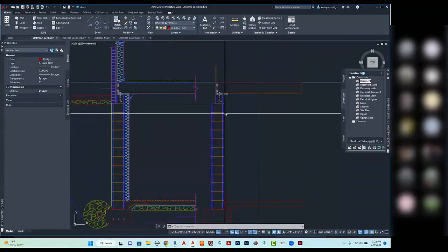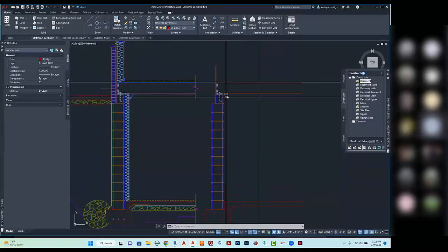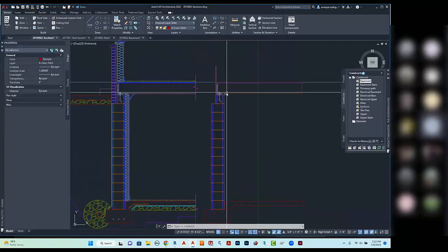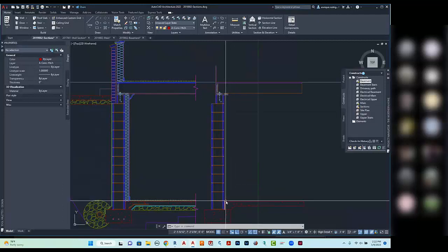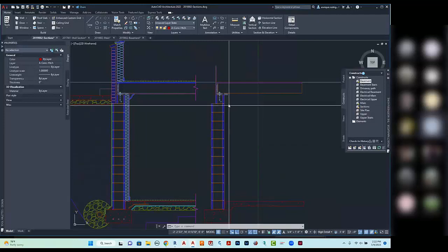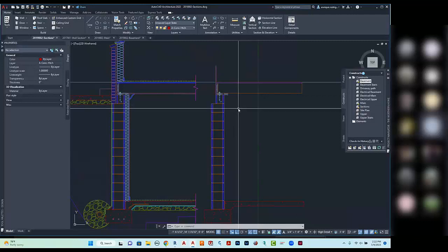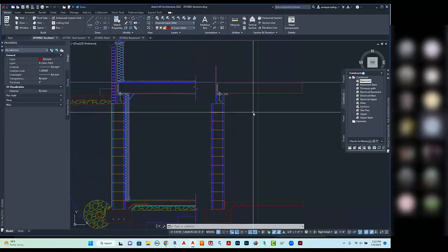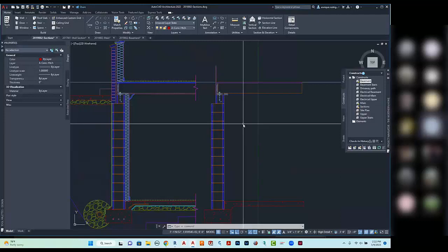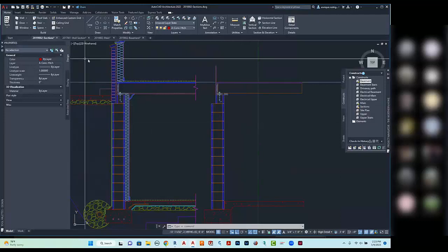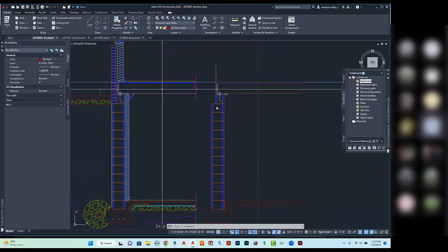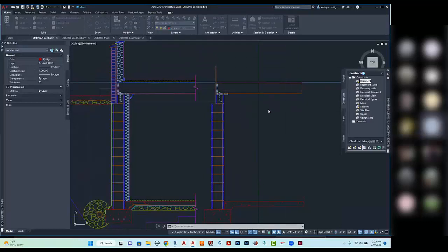All right, so just like the joists, these vertical elements between the top plate, the double top plate that we're going to have if it was structural, in this case, it's not, so we're only putting a single one, and the sill plate at the bottom are going to be what we call 2x4 studs, and they are spaced a certain distance apart from each other. Could be 12 inches, 16 inches, 2 feet. And again, we could draw them just to be complete, but we have to make sure that we're drawing them in elevation, because they are perpendicular to our view and we are not cutting through them.